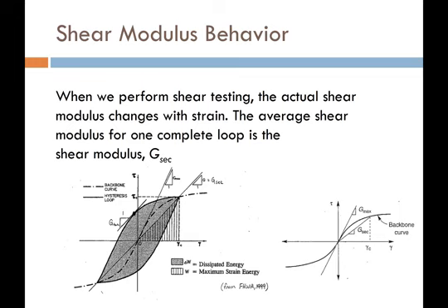And you'll recall this figure looks familiar. Remember how we said that the ratio of these areas, the area beneath the secant modulus curve represents the idealized energy from a single cycle, and also the energy here in gray, which represents the energy lost by the soil through friction and particle interaction.